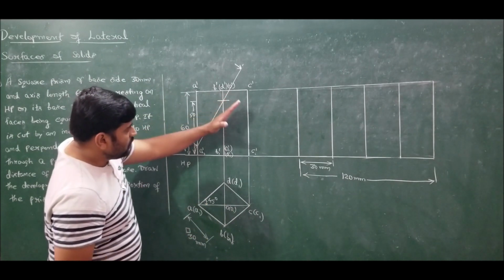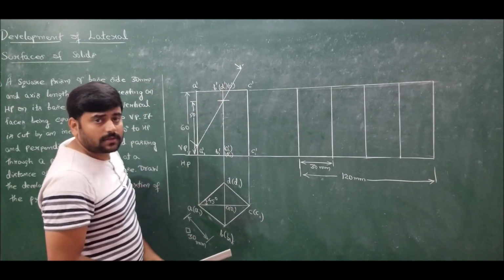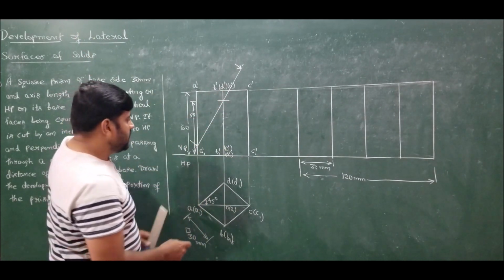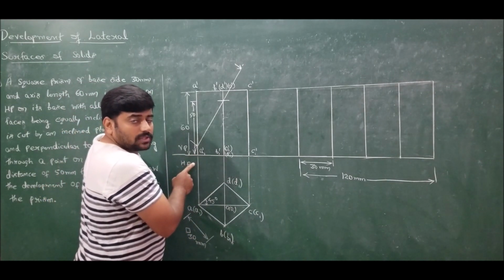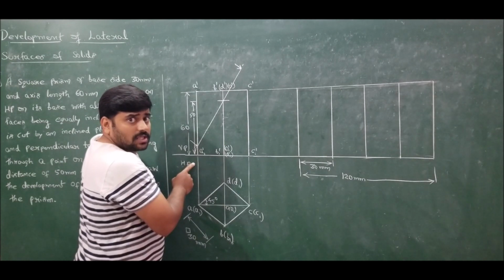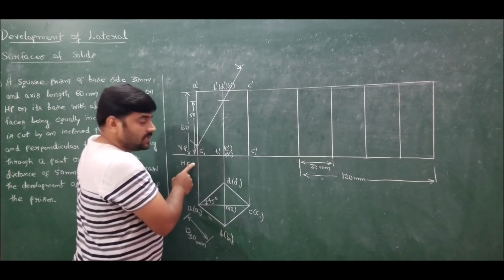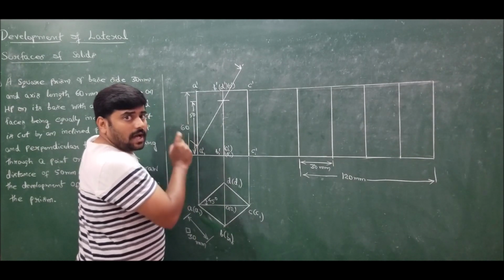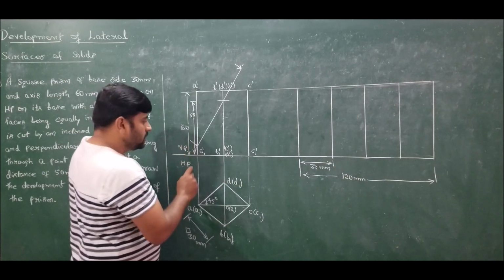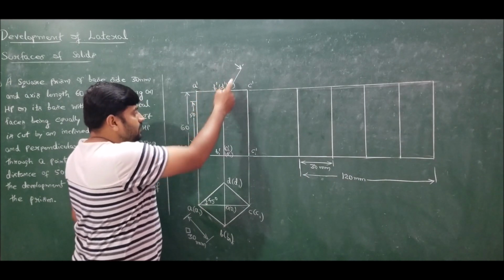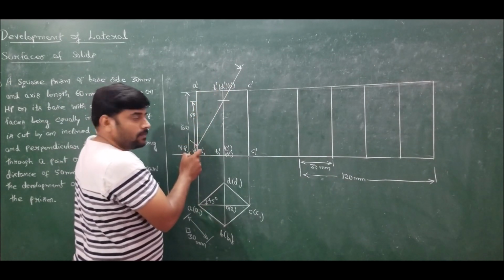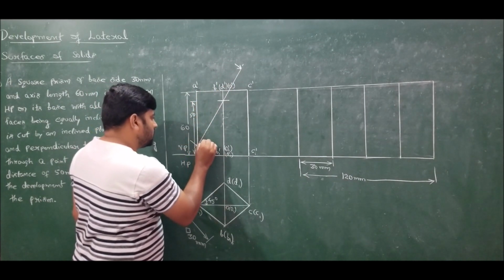So I want this lower portion, I should remove this upper portion. To do that, observe carefully, start from each corner, take both longer edges as well as side lengths, that is, the shorter base edges at the bottom as well as at the apex. Let us start from A. The longer edge of A is A1 dash, A dash. Is it intersecting the cutting plane? Yes, it is intersecting the cutting plane. Mark it as 1 dash.